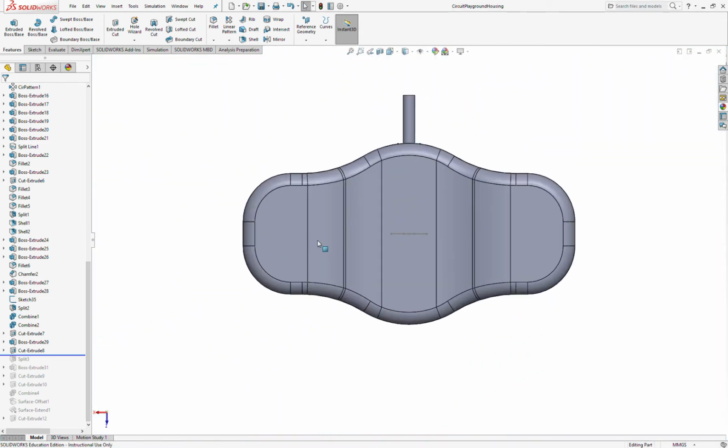One of the first things when dealing with screws is that you would actually pick out your hardware. Screws come in all sorts of standard sizes. We're going to talk about this in class. I don't have the exact date, but we are going to talk about hardware and how to select it and all of that. But the basic gist of it is, when doing screws in 3D printed parts, generally you're going to use some sort of insert for the threads.